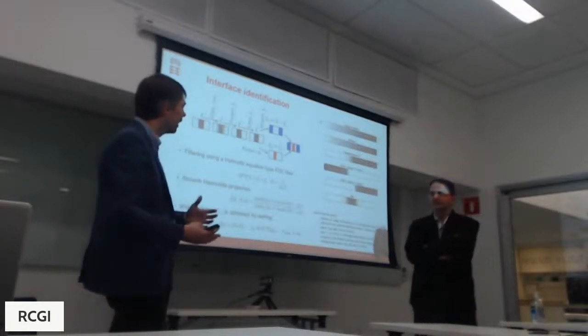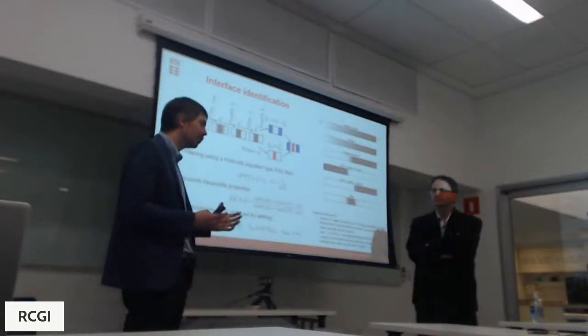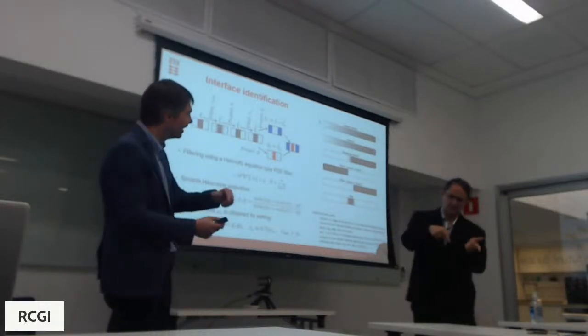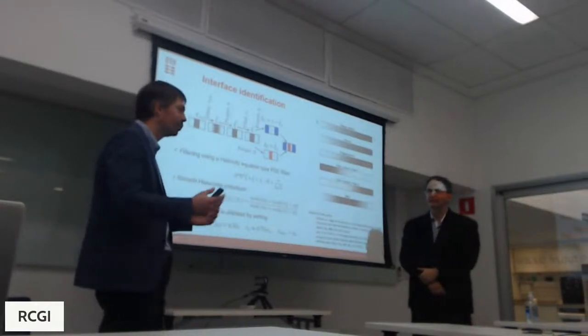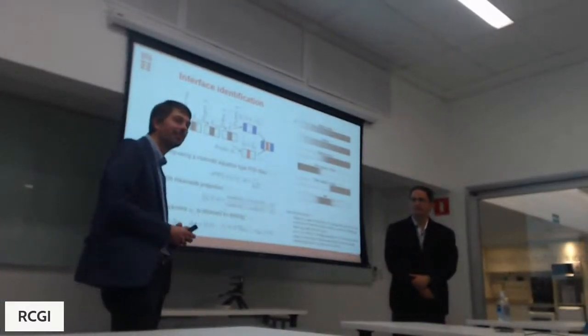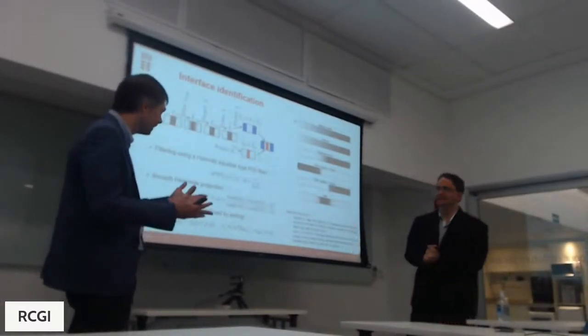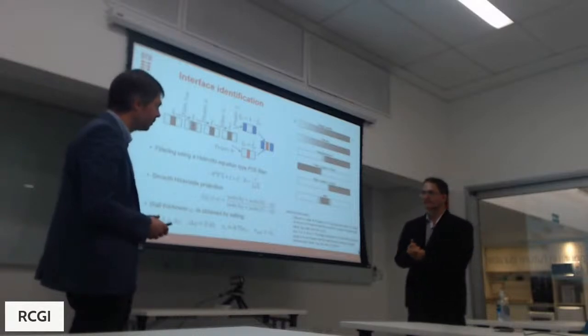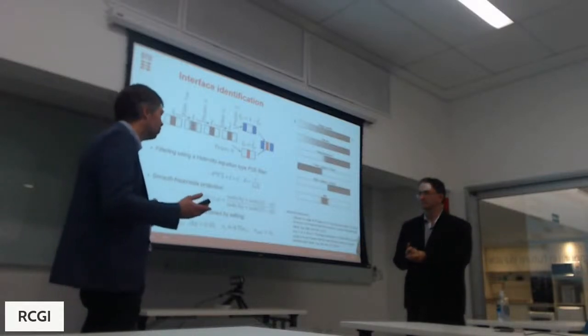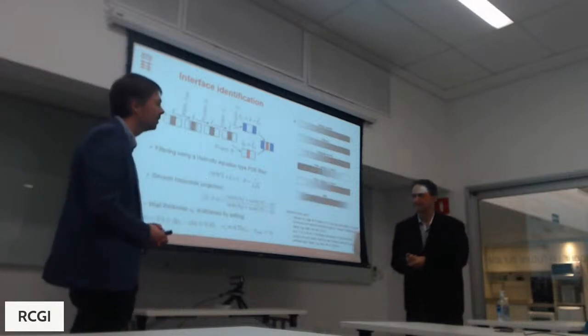So I see a more reasonable way is to work on the topology first, and then do a few sweeps of shape optimization, or find a method that can do both. Large mobility is the issue. For many explicit boundary capture methods, it's difficult to move over large distances.